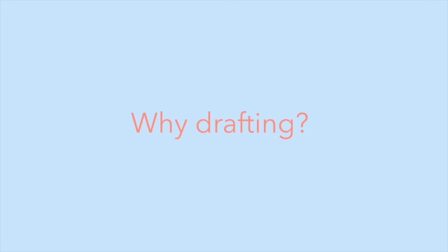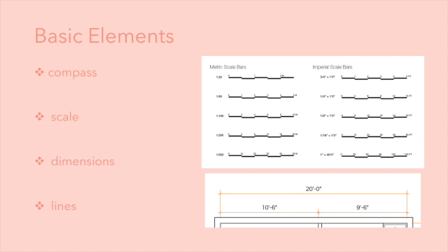So here are some elements that are typically seen in floor plans. A compass is needed so that whoever you're showing your plans to knows how the building is oriented within the larger space and in relation to north, east, south, and west. This is really important because you can use the orientation of the building to maximize natural light and heat, or you need to know wind patterns, or maybe there's a busy street near the northeastern corner of your building, and you need to figure out a way to minimize the noise that comes from the street into your building.